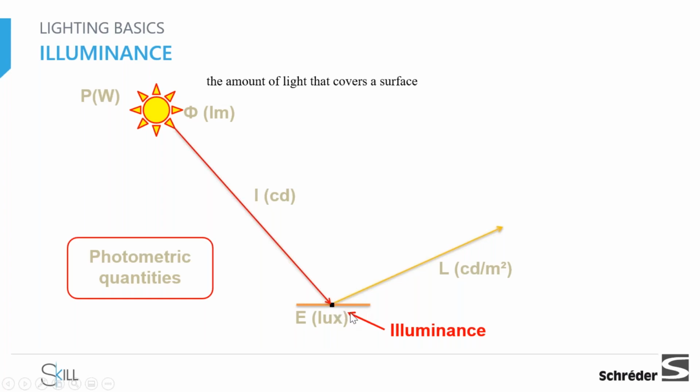We need to highlight here that the illuminance value does not depend on the surface. I mean, if we have asphalt, or a mirror, or any color of material, we will have the same illuminance value, because it depends on two factors only, which are the light source flux and the candela value. Maybe in some applications like indoor, it will depend on the walls, because there will be reflection from there. But in real life, in open space, there is no relation with any surface.